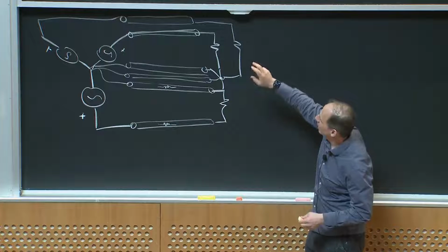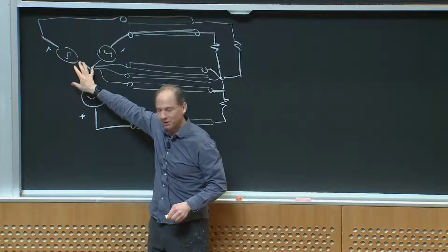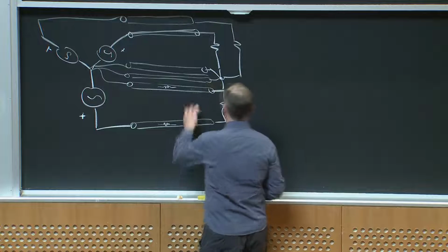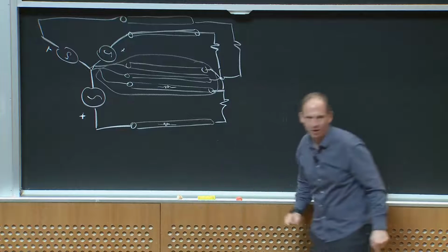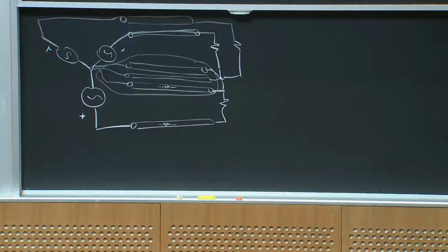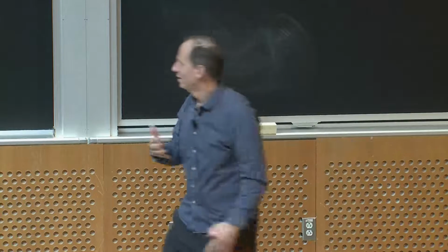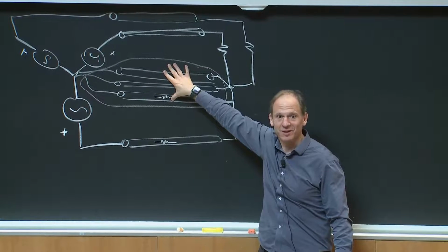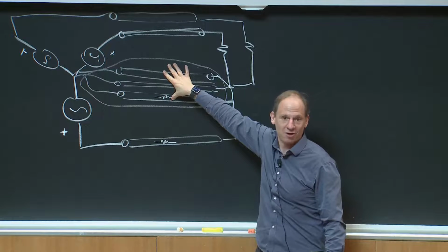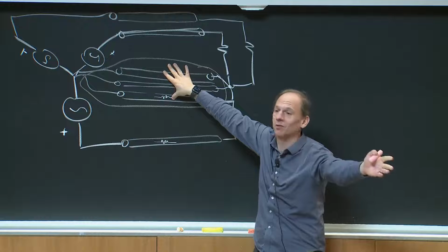But notice that all these 3 voltages and the resulting all these 3 currents add to 0, right? And that means that the net current in these center conductors is what? 0. So suddenly, if what I cared about was the copper loss to send power down the line, I can basically throw away half of my conductors for a 3-phase system instead of a single-phase system. I need half the copper to carry that much current, okay? And that is a huge advantage if your goal is to transfer power over long distances.